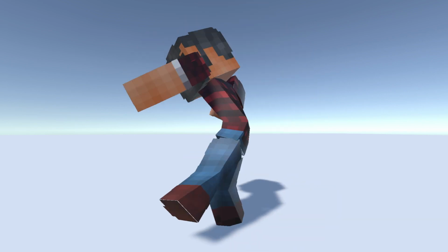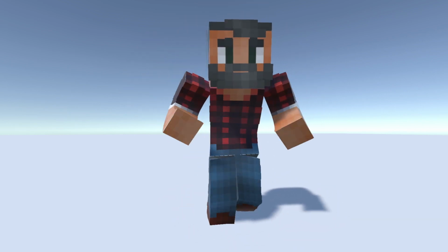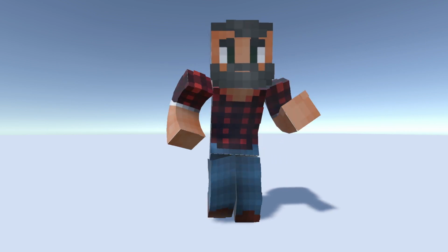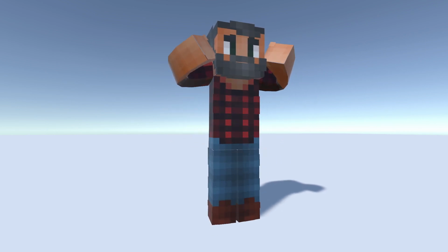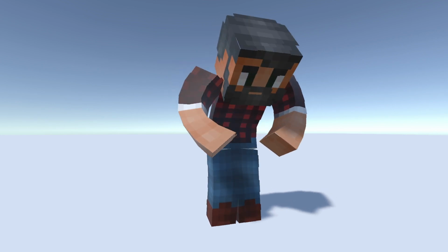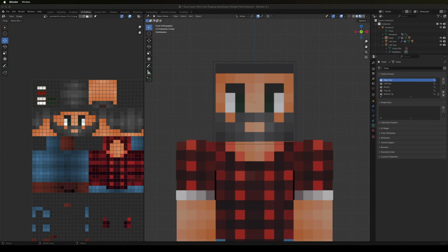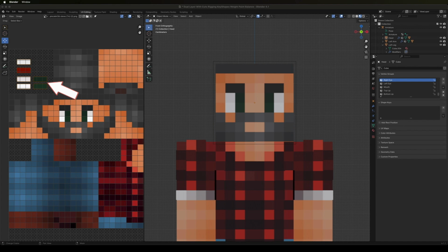Our most pressing issue is that our model doesn't have distinct facial features modeled into the head object. We'll address that issue by subdividing the character's face into a number of distinct regions and smaller subfaces that we can then group and manipulate as if they were facial features. In setting up our workspace for shape keys, we'll load a modified skin file into the UV editor. I've added an extra texture zone in an empty part of the file, which duplicates the eye colors and introduces a texture for the teeth and tongue.